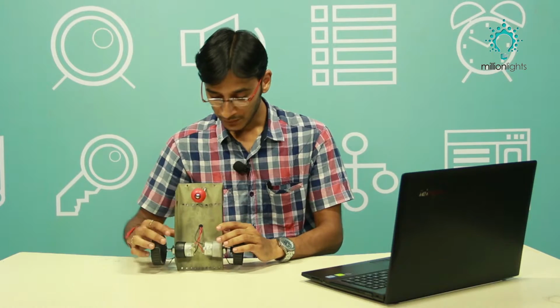Because if I connect a 160 rpm motor and another one is a 120 rpm motor, then if you want it to go forward, it won't go forward, it will go in the left direction or something like that. Or even if you take two 120 rpm motors but they are of different make, it can cause an error where it won't go in a straight line, it will go slanted, because both the motors do not have the same torque and same power. So we have to take care of that. So take two motors which have the same torque, same rpm, same voltage, made by the same company.